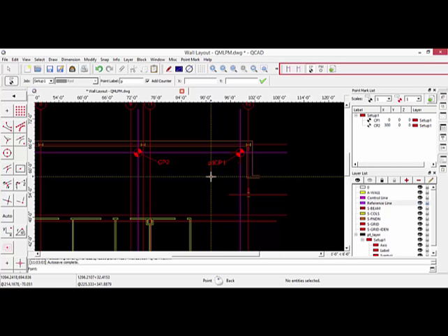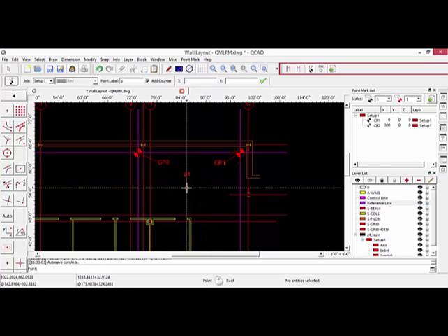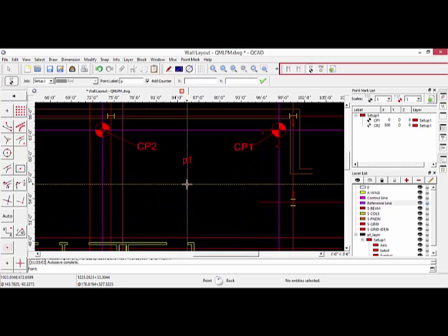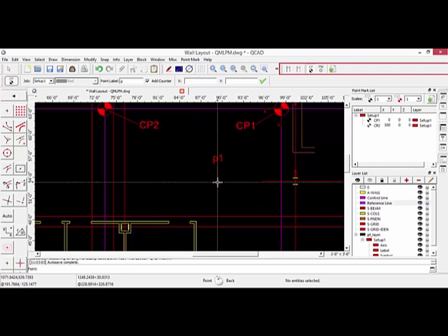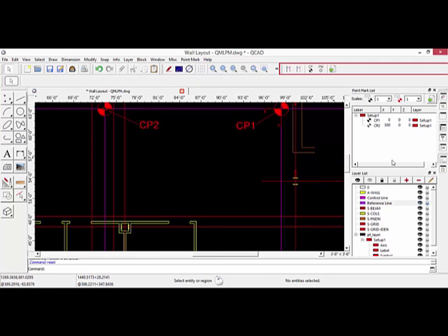After it does control points, it's ready to start my point marks. Now you notice my cursor has a label on there, it's a 0.1, so it automatically does take me into the command to establish my first point. So I'm going to reset. And I'm going to show you right now under the point mark list that it has established my first 2 control points. You can see the actual symbols on there are different. And the X, Y, Z coordinates are there as well. And these are all in inch format. So we put in 25 feet. You see the 300 feet option in there.